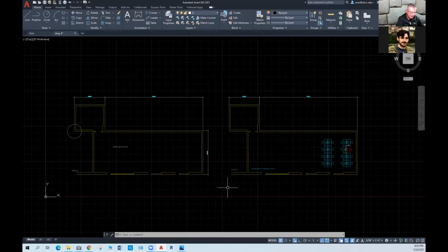And then we get another variable called MSLT scale. This is a model space line type scale variable. And so same thing. This MSLT scale is the scale that we have for annotative objects. And that's the scale you see at the bottom right corner of AutoCAD in model space. It's a switch for that.